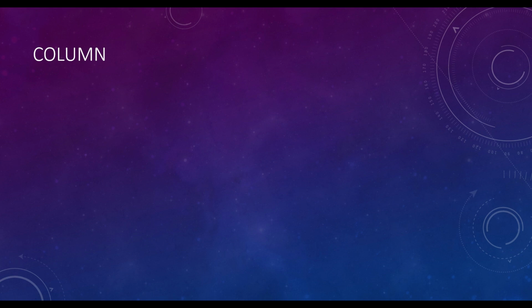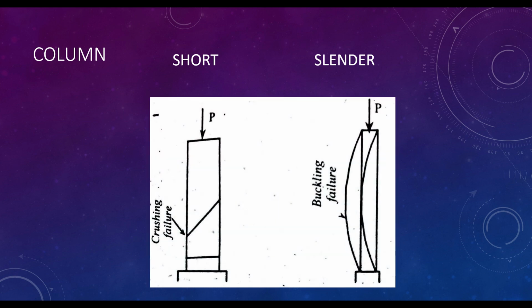The classification of a column as either short or slender is governed by the geometry of the column, and we use the term slenderness ratio to determine if a column is short or slender. A short column tends to fail by shear or compression failure, which can result in crushing, while a slender column, as a result of the length of the column compared to its size, tends to deflect a little bit. This deflection results in buckling failure.